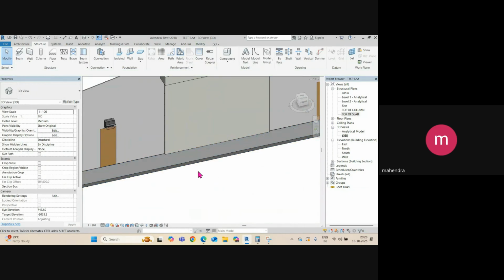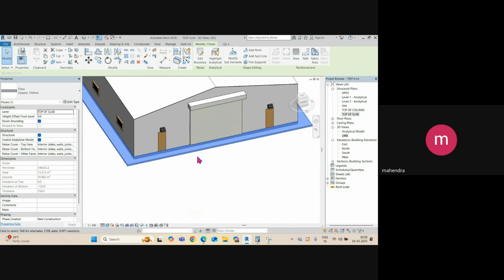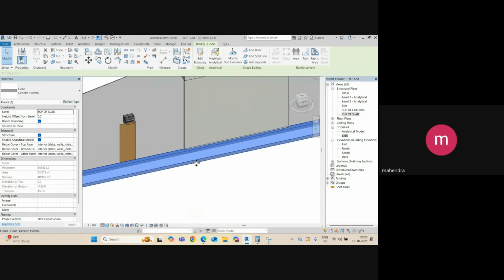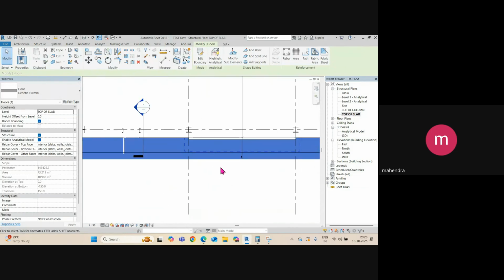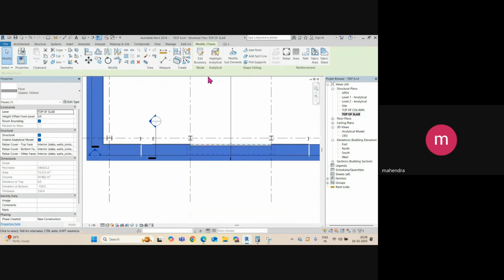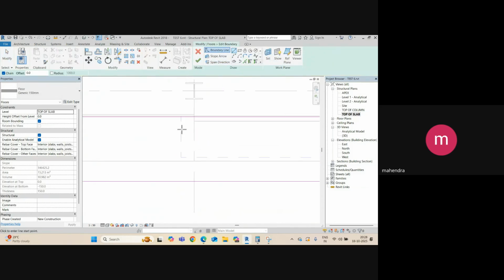Okay, and suppose this level is above and the ground level is a little bit below, and you want to give vehicle access through this building. So you need to add a ramp here, right? So how to add the ramp? Don't use the ramp command for a short ramp. First of all, select your footpath print, right, and close this shape here.